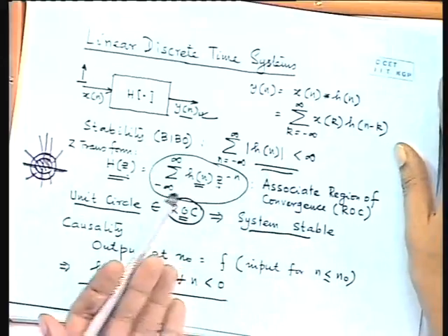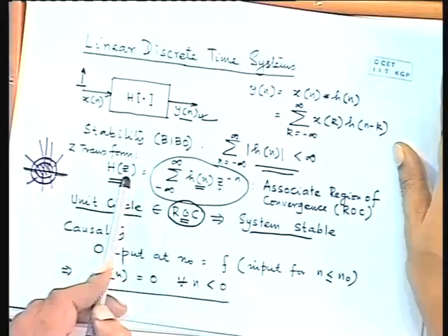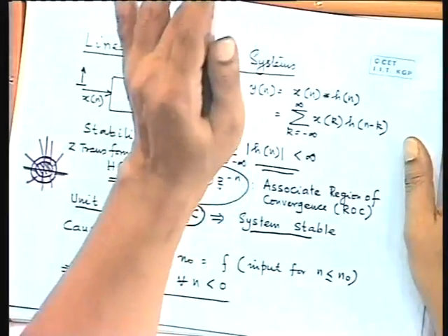For example, I will presently show that given an H(z), you can have various impulse response sequences which will give the same H(z), but some of them are going to be causal and stable, some of them are going to be non-causal and unstable. In this course we will implicitly always choose the causal and stable sequences, although mathematically speaking you can get any one of them.